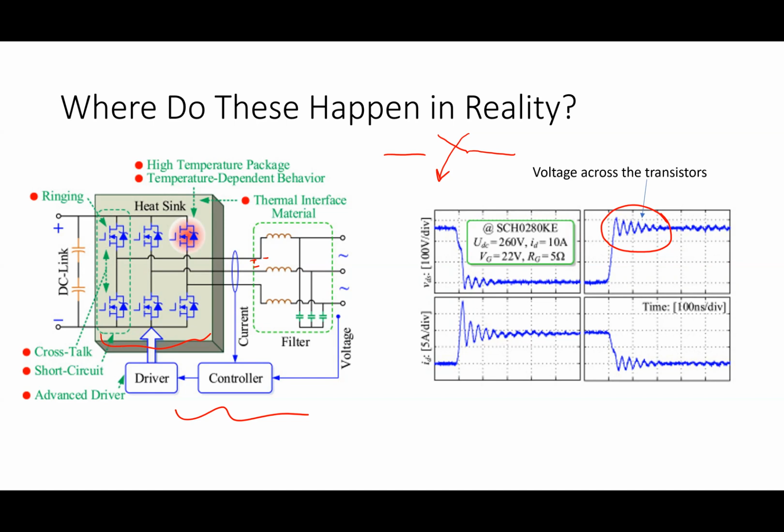If I have a second order response, right, what does that mean? How many energy sources do I have? Two. Typically one of them is an L and one of them is a C, right? It could be two L's, it could be two C's, but usually it's an L and a C. And in this case, I said, if I had just a purely LC system, just an L and a C, I call that an undamped system, right? If I have an undamped system, there's no what in that system, we said the other day.